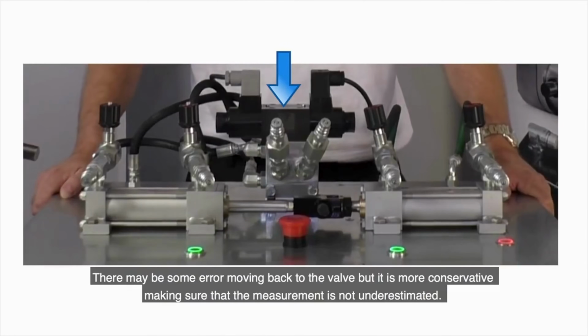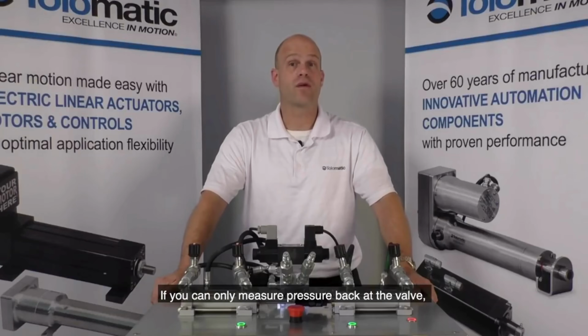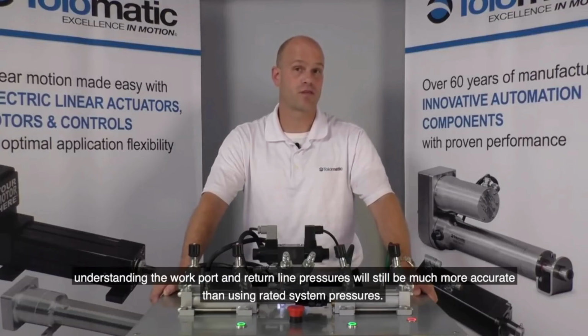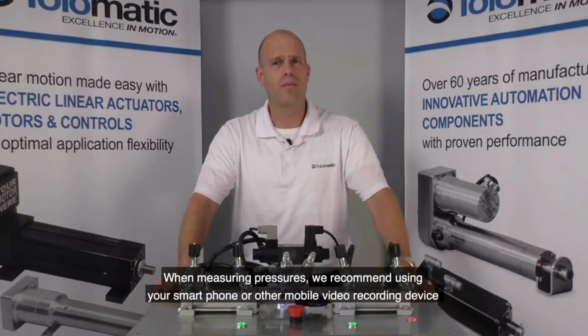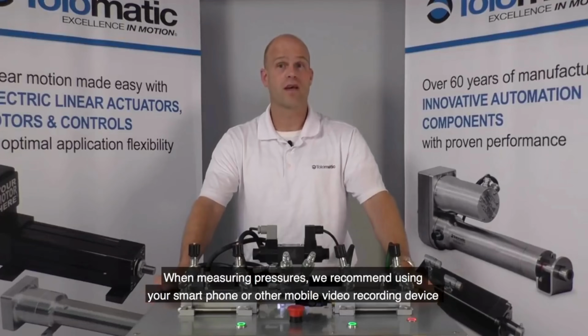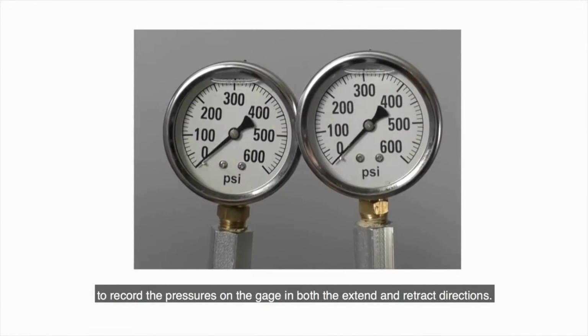There may be some error moving back to the valve, but it is more conservative, making sure that the pressure measurements are not underestimated. Even if you can only measure pressure back at the valve, understanding the work port and return line pressures will still be much more accurate than using rated system pressures. When measuring these pressures, we recommend using a smartphone or other mobile device to record the pressures on the gauge in both the extend and retract directions.